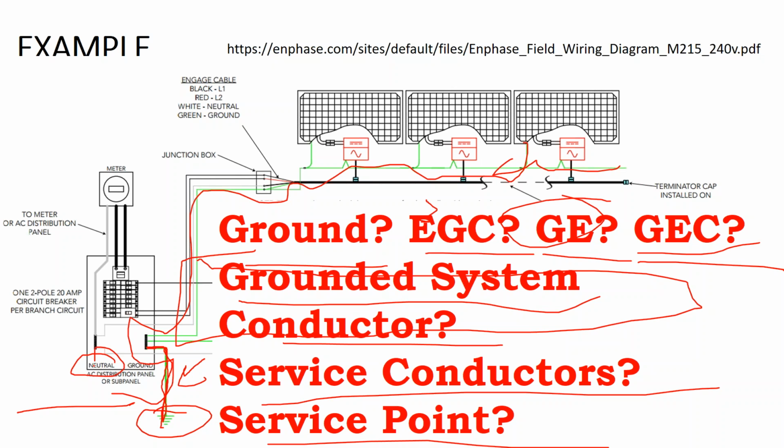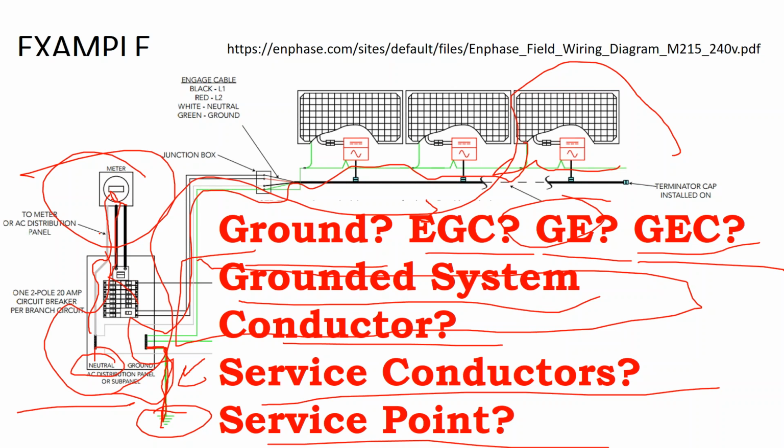So there are special rules regarding when you connect the neutral to ground, and as a rule of thumb, the neutral to ground should only be connected at one point. If you are connected to your utility, usually that neutral to ground connection is made in the meter can, where the neutral may go all the way up, and then they bond the neutral to ground here. So it's a reference point. That means in your neutral, you might have some power going, and eventually it goes all the way down into your grounding system, but it may not have that voltage at a different point on it. And eventually we'll see that the neutral and ground voltage difference helps our breakers function.